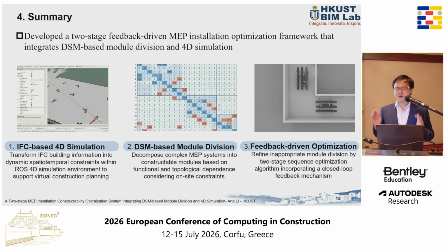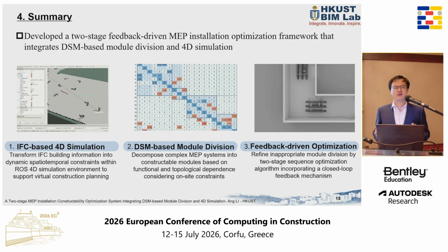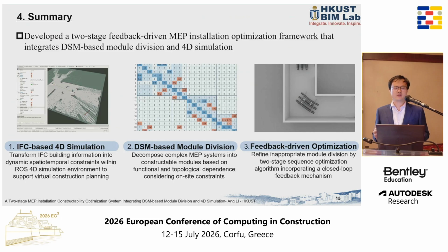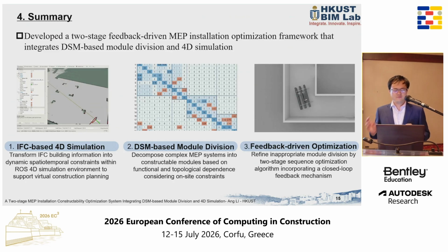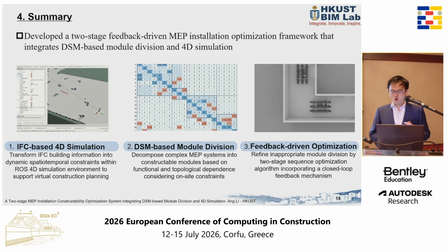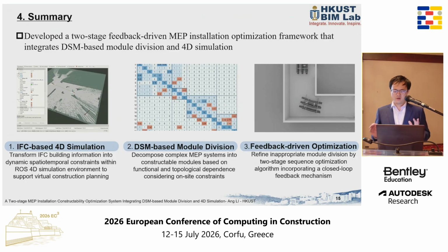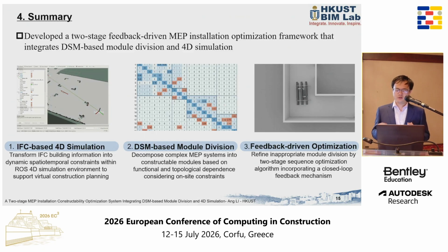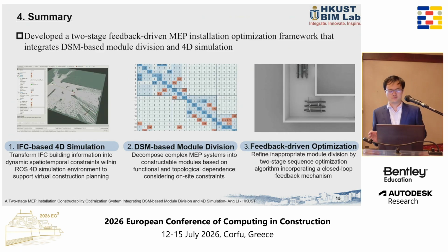Finally, let's summarize our research. We have 3 contributions. First, the IFC-based 4D simulation; then the DSM-based module division; and finally, feedback-driven optimization. Within this feedback mechanism, we can refine the improper module division using the trajectory information, thus enhancing the overall constructability of the installation plan.